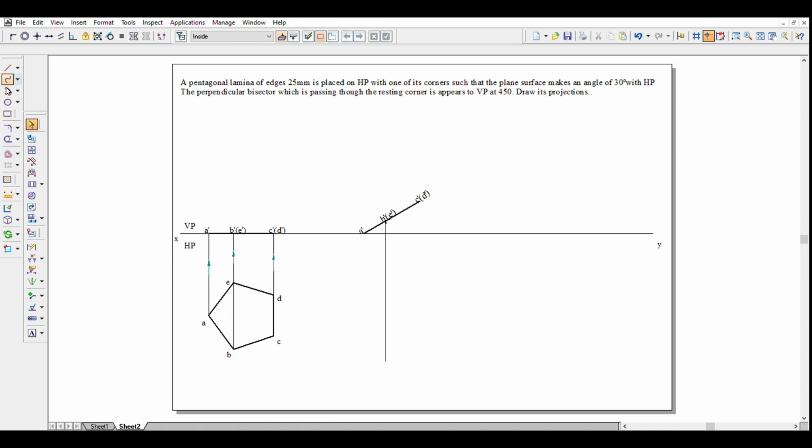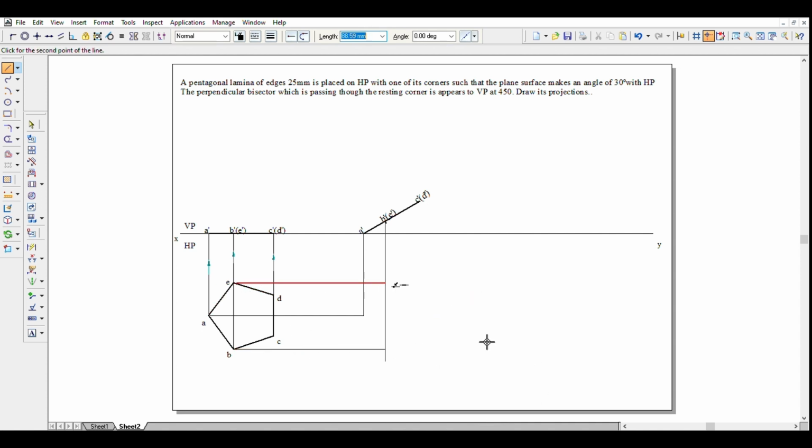From there I have drawn an extension line and now we can do the same from A also, and because it has to join here we can use the dimensioning, until A, so we can join here to A so we get the exact point. For B and E also we have this line we have constructed. We have E, we can join it, and for C and D we can use this alignment and place it near C. We can join it to point C, and from D we can extend it again up to the line.